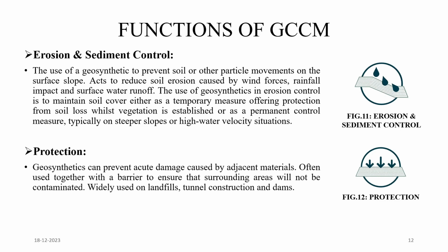The use of geosynthetic in erosion control is to maintain soil cover, either as a temporary measure, offering protection from soil loss until vegetation is established, or as a permanent control measure, typically on a steeper slope or in high water velocity situations.